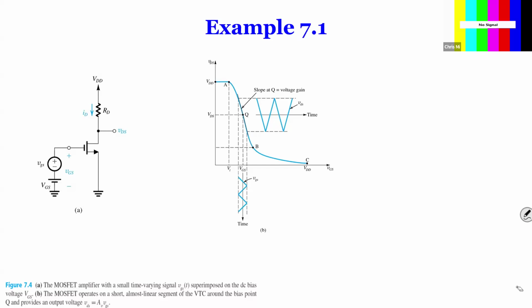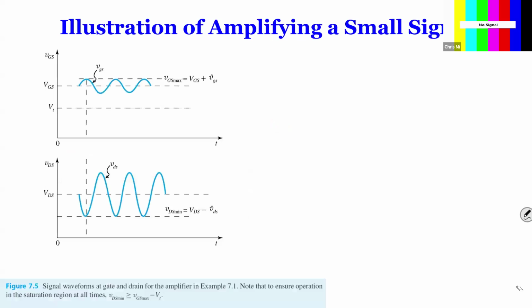Right? So if you work at this point, up is okay, but when your signal becomes negative, you go here, that's not good because you're already out of saturation. So biasing is important. Often we bias in the middle point, between A and B. A is the cutoff point where VGS has to be larger than VT, otherwise it's going to be cut off. But above VT, getting to VB, you're out of saturation, you go to triode mode. So between A and B, we try to maintain the middle. That's just some concepts visualized for you guys.